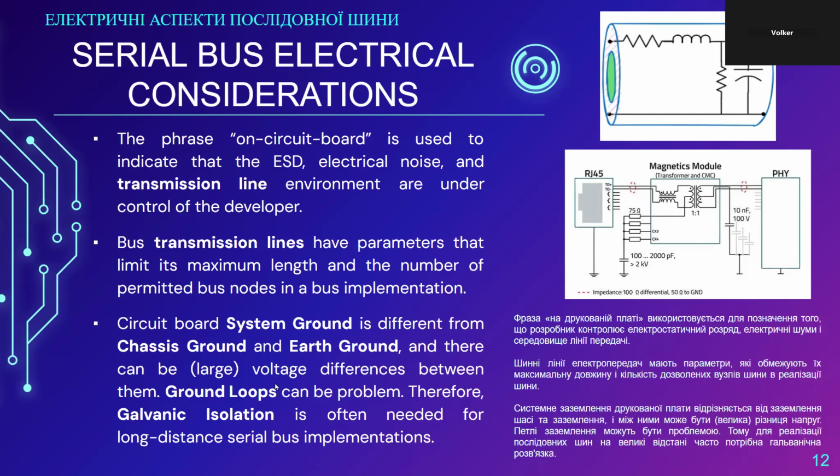You never know how an electrician has wired up a house. Sometimes they make mistakes, and there are outlets, even in the same house or building, where the neutral and the earth ground are connected the wrong way, and people don't notice because nobody ever uses devices that are connected between buildings or between rooms.